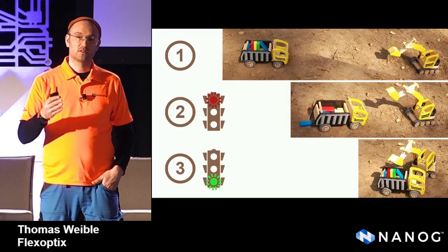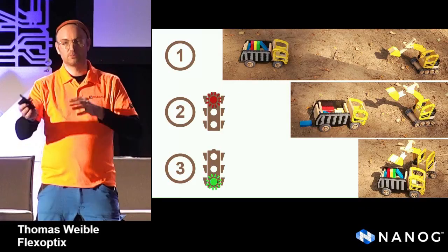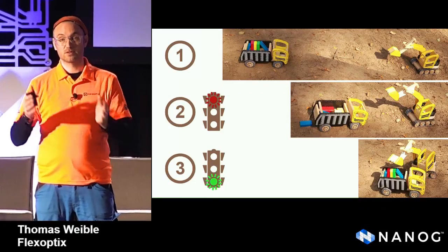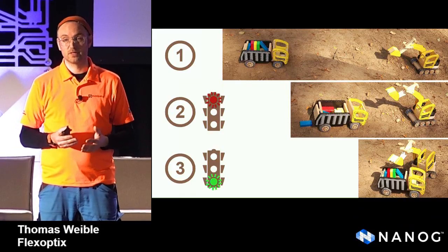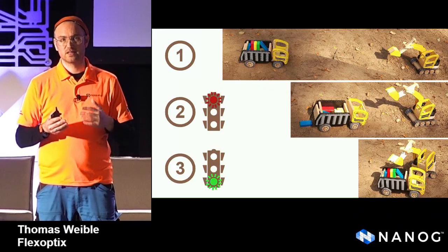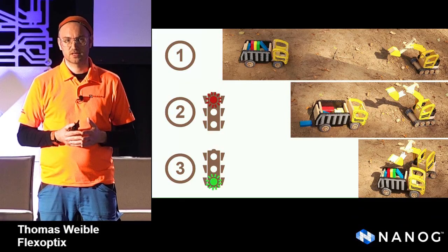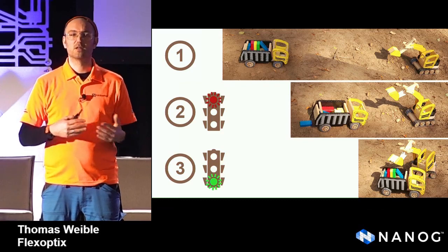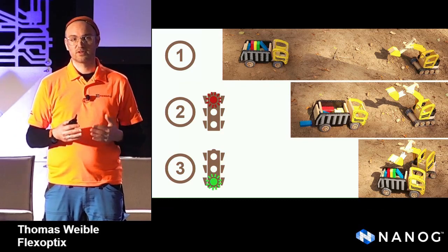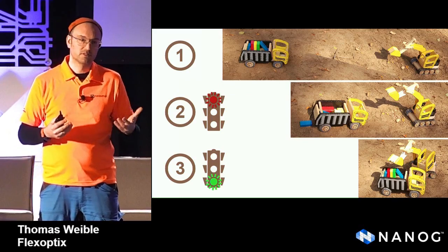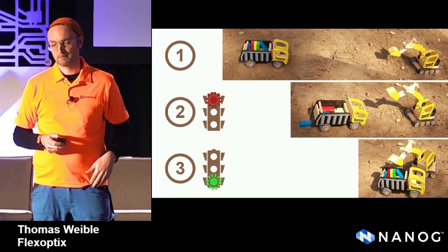Now you can imagine that this excavator takes a little bit of time to get all the bricks back in order and sort them, and also FEC needs time to operate. So in total you get an additional delay of around 100 nanoseconds on your 100 gigabit link when you enable the FEC. That's something to bear in mind. So you need to give the FEC a little bit of time to operate.